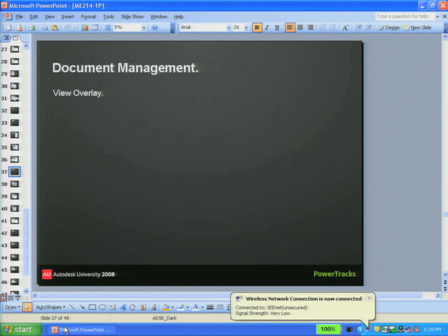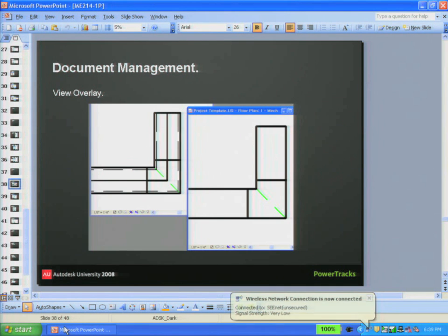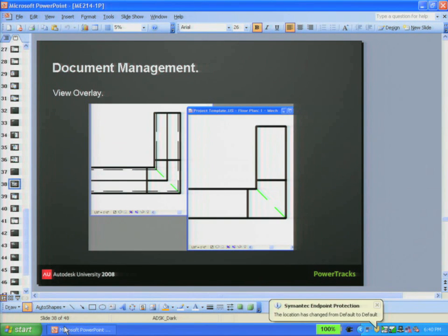And next thing is view overlay. The left side is exactly the same ductwork. The left one is the wireframe view setting with a 2-inch lining on that ductwork. And the right side is the exact same ductwork with a hidden line view setting. But obviously when you plot it out, you don't want a wireframe view setting because the line is not breaking when ductwork is on top of each other. But then how do you show the lining on a ductwork? You've got to draw it. How do you do that? So that's the one challenge.